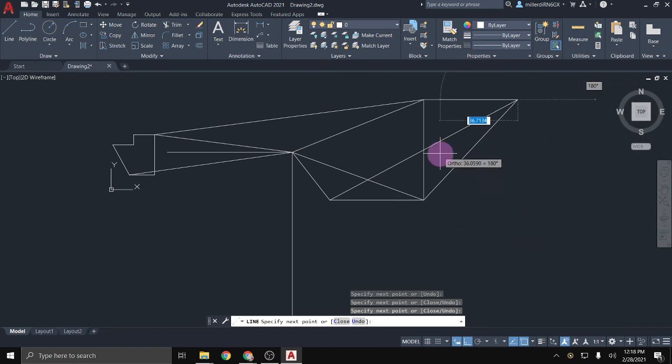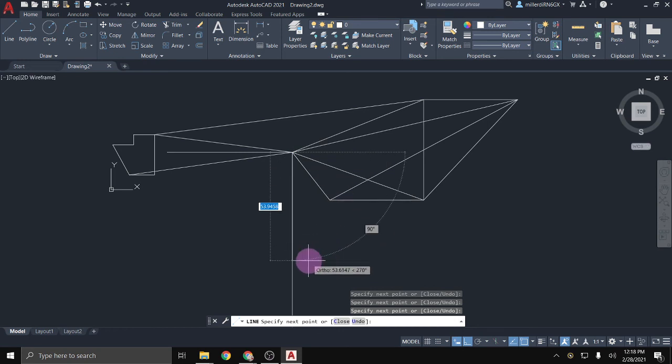If maybe I wanted an object snap that wasn't popping up, so for example, I turned midpoints off, but now let's say I do want the middle of this line. The issue is that anytime I see one of those green shapes pop up, so for instance, my cursor is nowhere near that point, but because that shape's popping up, if I click right now, it's going to snap to that point.